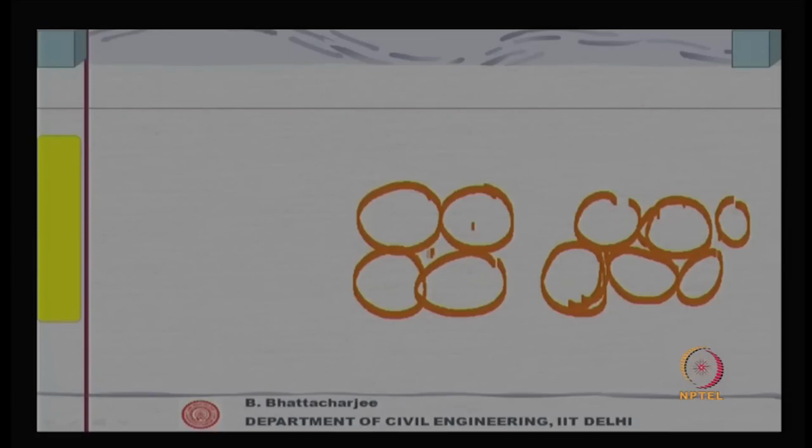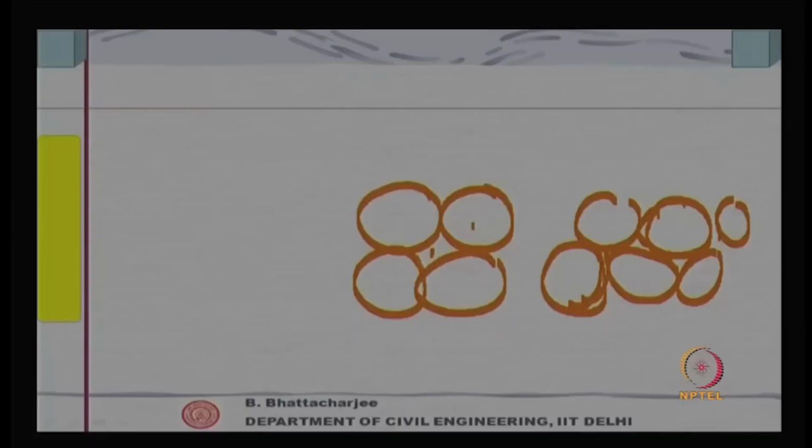governs the void content, and in fact, if I have a single sized particle, the maximum packing that I will obtain or maximum packing density that I will obtain, we will define maximum density later on. Maximum packing density that I will obtain will depend upon the nature of packing. This is of course, for spherical particle.